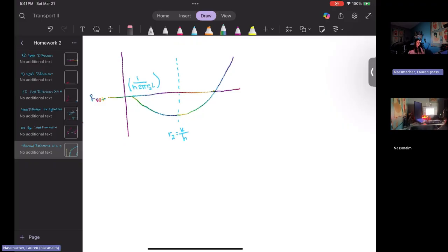But what we can gather through this graph is that as we add the insulation, there's going to be a point in which the insulation actually decreases how it keeps heat in or keeps heat out, right? So it's actually going to be less efficient if we add that insulation. But then eventually we'll get to a point where we're adding enough insulation to where it's helping. So you just have to find this critical point that shows the perfect amount of insulation to perfectly insulate the pipe.